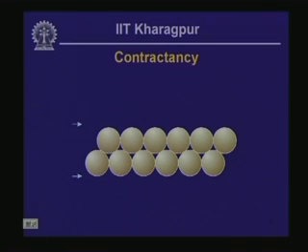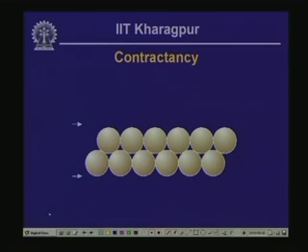So if you have a specimen which was originally loose, then if we apply shear stress, we are going to reduce the void ratio, and we are going to end up with a much denser assembly of individual soil or rock fragments, and that is indicated when you compare the top level of these spheres with the original elevation of the top indicated by the arrow at the top of this particular screen.